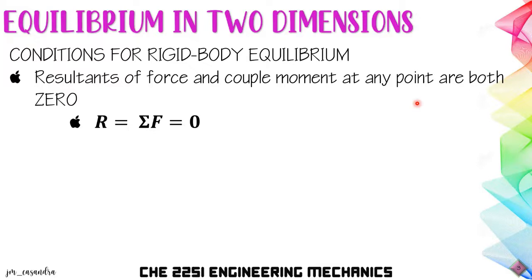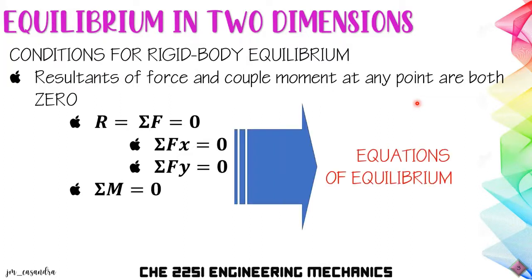Since it's two-dimensional, this pertains to the summation of forces along the x-axis equal to 0 and the summation of forces along the y-axis equal to 0. And also, the summation of moments at any point is equal to 0. These equations are called the equations of equilibrium.